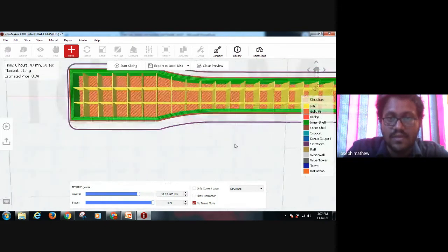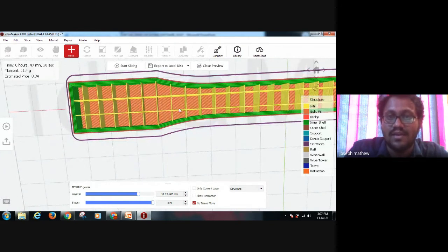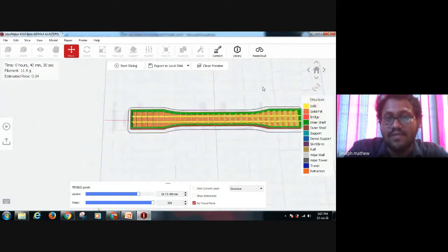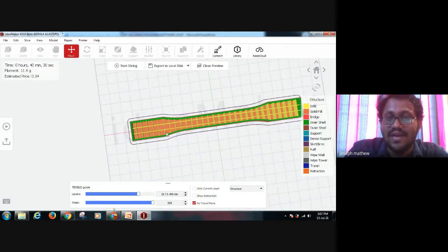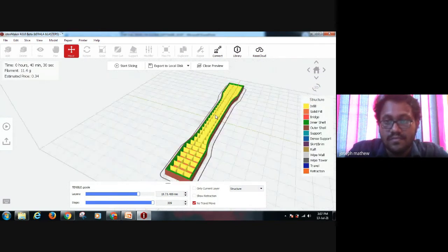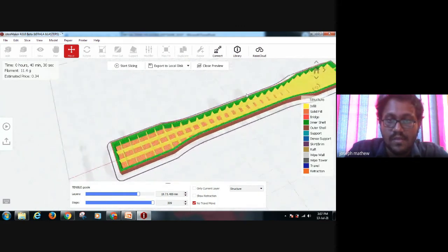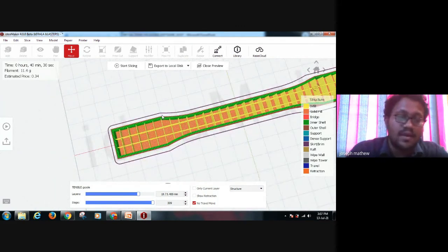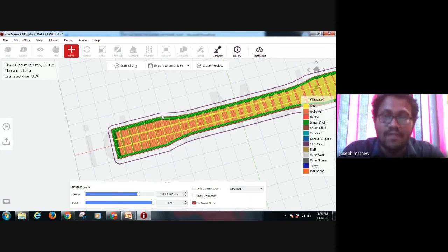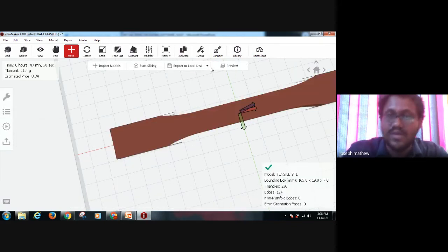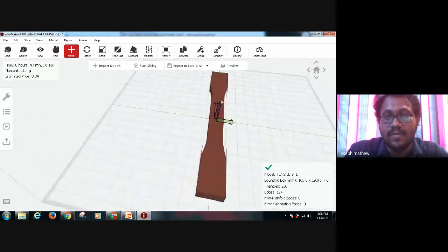So see, this is how a 0 degree and 90 degree infill grid pattern will look like. In case I am giving 45, 135, the grid lines will be in a 45 degree angle. So each of these has its own effect after 3D printing. The part strength can vary on different infill patterns, and even the angle given to infill can also have an effect on part strength, which can be studied in detail for different processes.